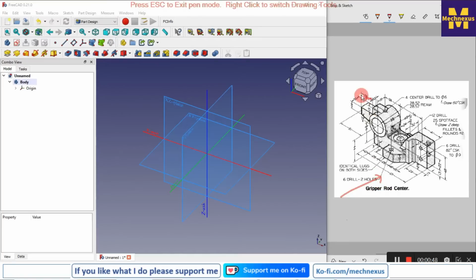So we will draw this front view on our XZ plane, and after that we will create the rest of the features, and we will try to make the part symmetric as much as possible, because when you make the part symmetric, then it is very easy to edit the part.